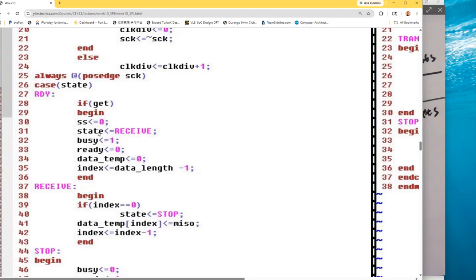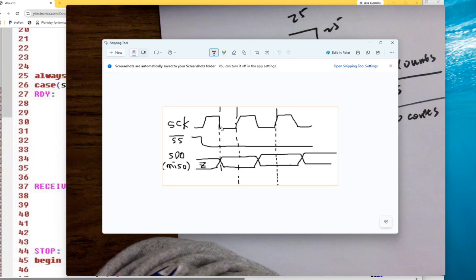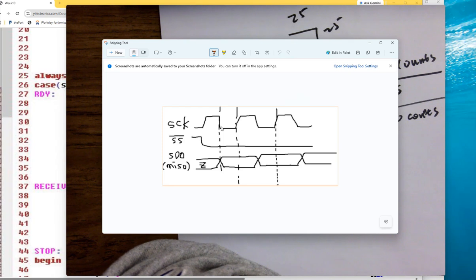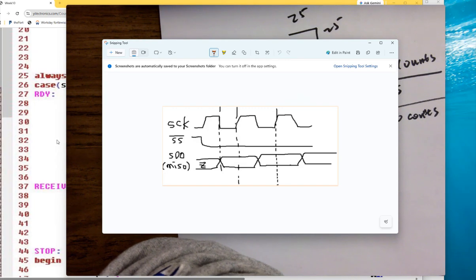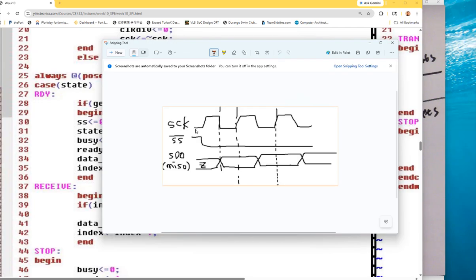Let me start over again, okay? So this is the leader receiver, and the rising edge and falling edges are defined by the leader receiver, because I programmed it that way, as the FPGA is hard coded with it. And it's a leader, so it enables, because the leader is in charge of enabling things and in charge of sending out clocks. So the very first rising edge of the clock enables it. That makes sense, because this is what we are supposed to do. Rising edge enables it. Okay? So which is enabled? The follower. The follower is enabled.